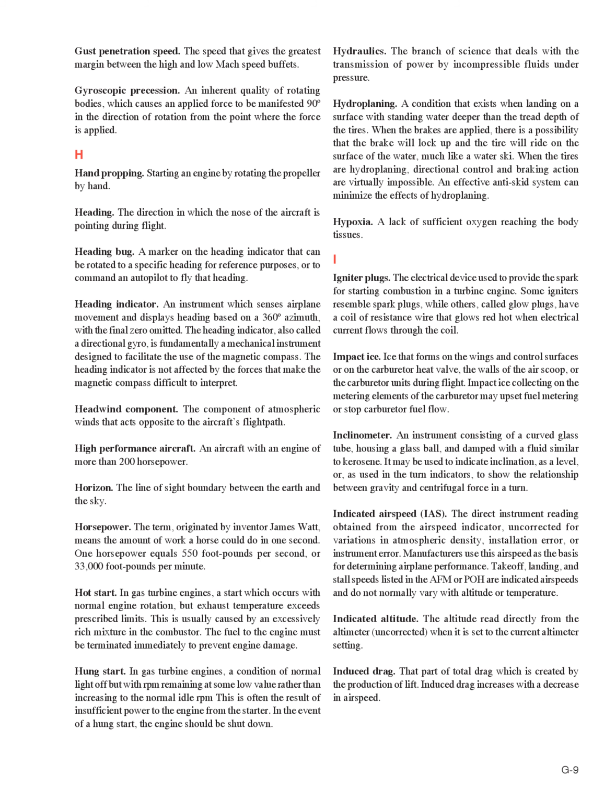Hung start. In gas turbine engines, a condition of normal light off but with RPM remaining at some low value rather than increasing to the normal idle RPM. This is often the result of insufficient power to the engine from the starter. In the event of a hung start, the engine should be shut down.